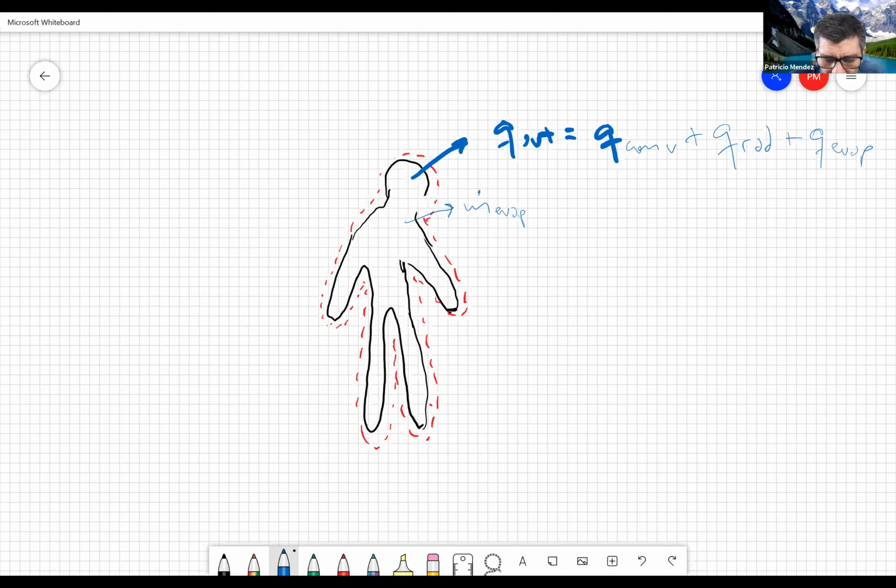So we have Q in, let's say there is no heat coming in. Let's say this is surrounded by an environment at 20 degrees C. The surface of the skin, we said, was 33 degrees C, right? And let's say Q in equals 0. Let's say we're in steady state, in which this lady is not getting colder and colder, or hotter and hotter. So if it is in steady state, Q stored equals 0.